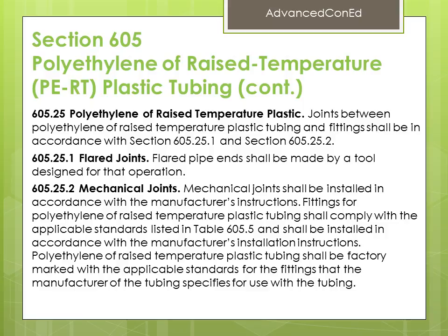Fittings for polyethylene of raised temperature plastic tubing shall comply with the applicable standards listed in Table 605.5 and shall be installed in accordance with the manufacturer's installation instructions. Polyethylene of raised temperature plastic tubing shall be factory marked with the applicable standards for the fittings that the manufacturer of the tubing specifies for use with the tubing.